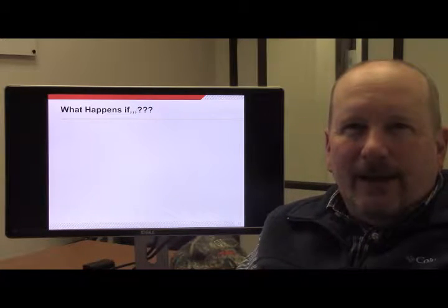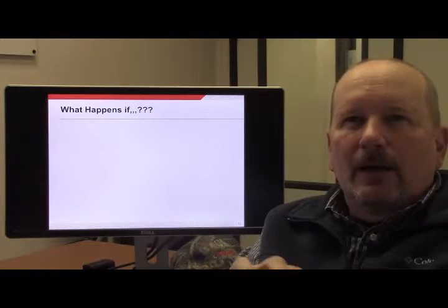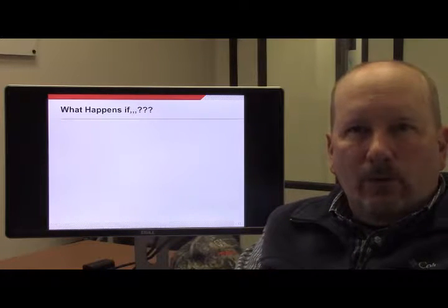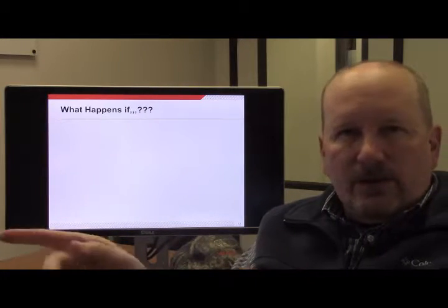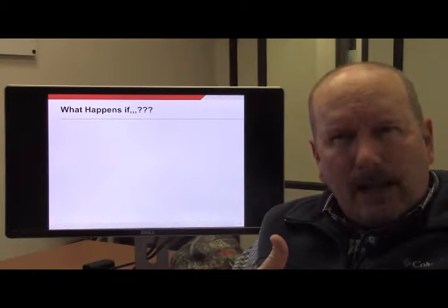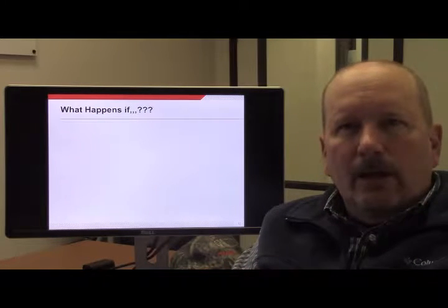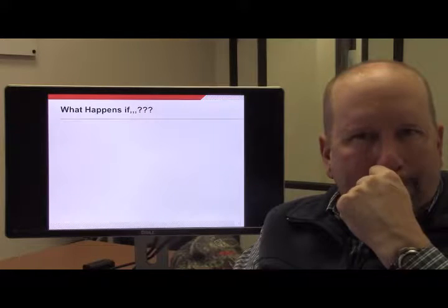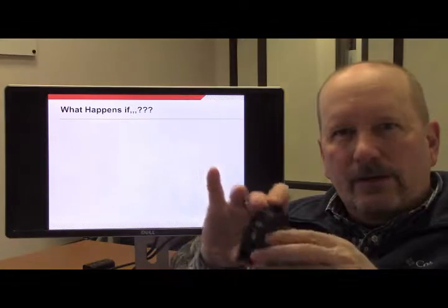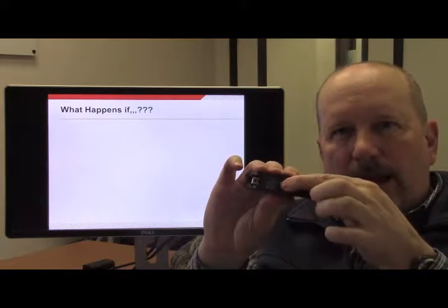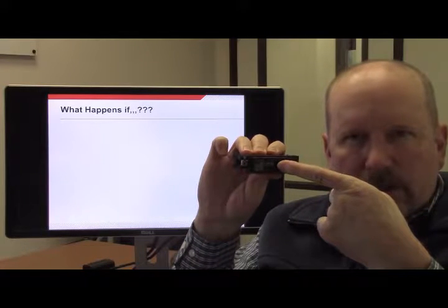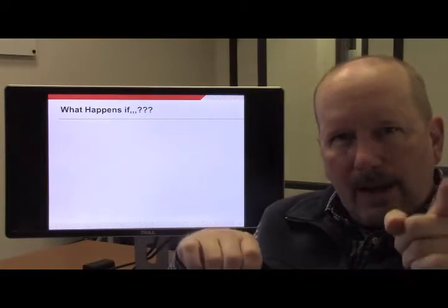Can't get anything. And unbeknownst to me, someone has taken a paper clip, opened it up, folded it over, and jammed it into one of the wall outlets in my house. And it's on the same circuit as my television. So there's, in effect, a bolted fault. But I don't know that. And I'm impatient. So I go and find the AC panel in my house. I find the particular circuit breaker for that circuit, and I see it's tripped, and I close it, and I hold it in the closed position with my finger. What happens?